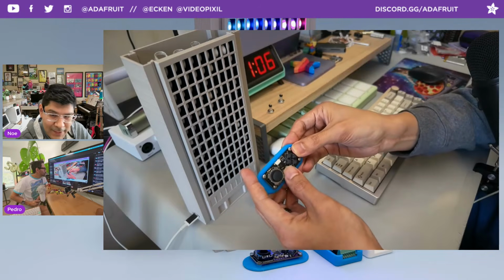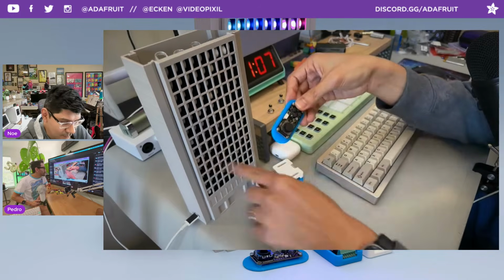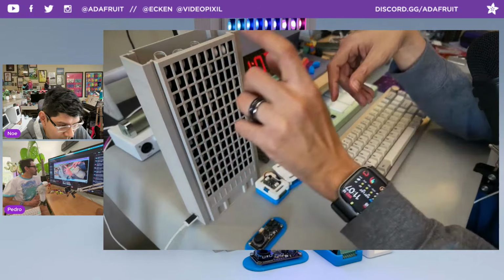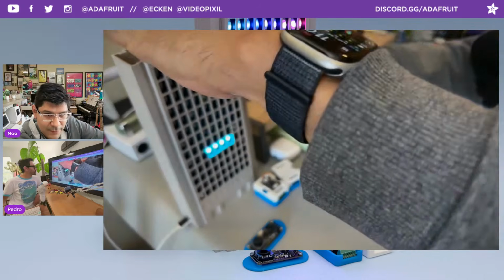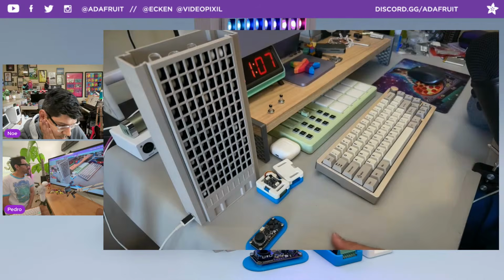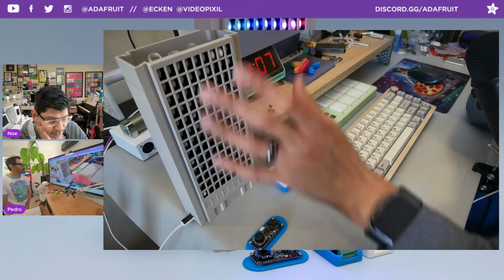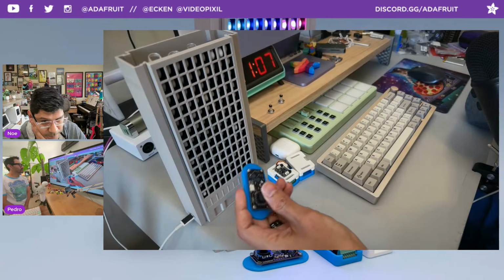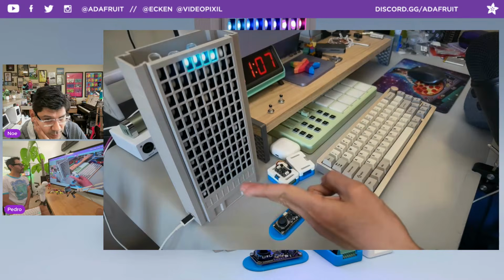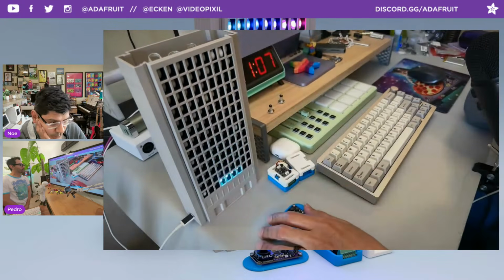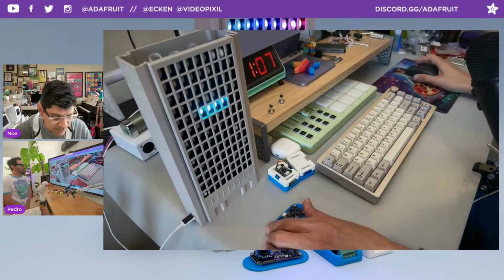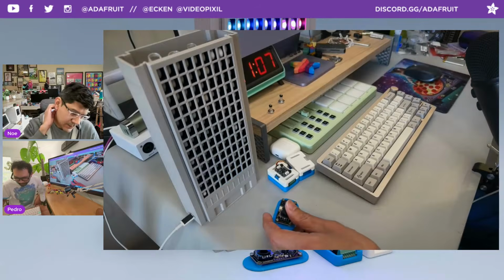And I think you have start and select here in the middle. So we'll be able to pause the game, play the game, rotate the blocks, and then put them in the right spot here. There's going to be a piece of black LED acrylic that gets sandwiched in between the grid and this top frame. And I think that's about it. There's not going to be any sound effects because we don't want to do sound effects for this one. We just want to keep it as a simple, playable Tetris game with a little gamepad here. And the only soldering you'll need to do is, I think, just cutting the stock cable that comes with the NeoPixel Pebble strip, tinning the wires, and then screwing them into the block terminal on the Feather RP2040 Prop-Maker. So I think that's pretty much the gist of it.